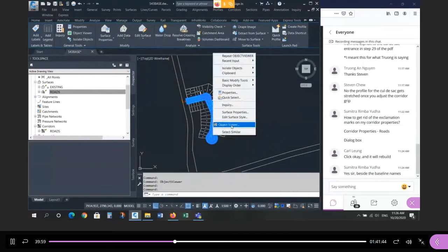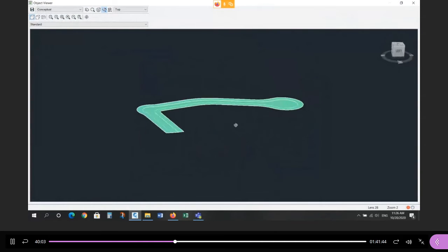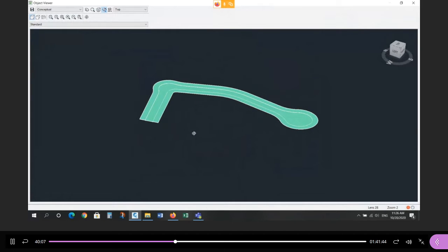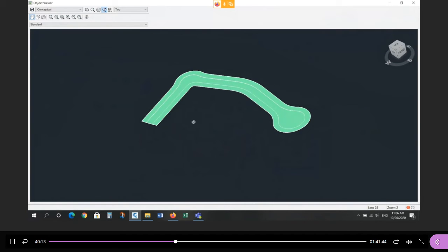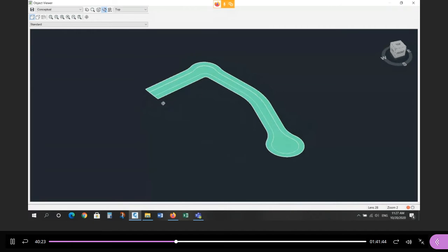And look at the surface in 3D, object viewer. That's pretty good, not a bad surface. So that's what you're looking to do to create this finished ground surface. This surface is used for the front lot corner elevations, which I'll demonstrate again in a moment, and it's used for the top of maintenance hole elevation when you do your pipes down on the pavement. So that has to be good. The only thing I didn't do is the entrance, the elevation, the curves at the beginning.